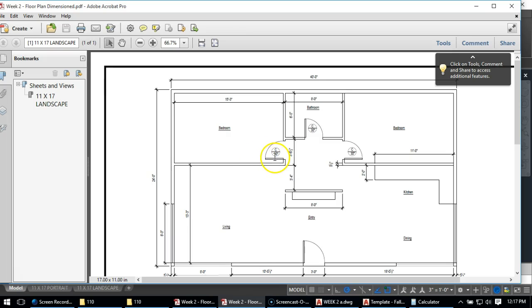And also we'll need to know the thickness of the door. By that, I don't mean from here to here like 3.0, but the actual piece of wood or metal or whatever the door is made of, from there to there. And for that, let's just keep it simple and do 1 3/8. Usually there's typical door sizes, 1 3/8, 1 3/4 might really be the exterior door, but that's all handled in notes. So for your AutoCAD drawing, it's not entirely important to do that.